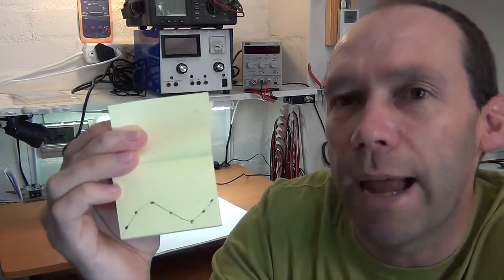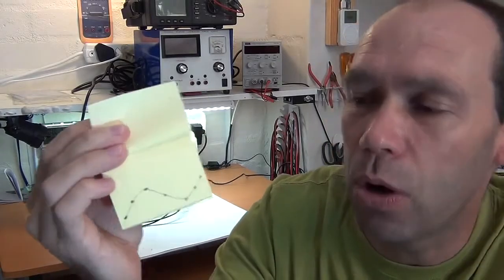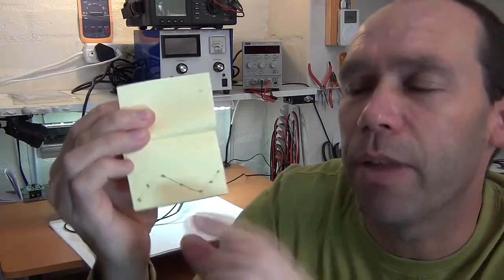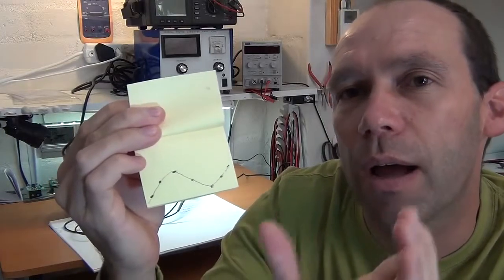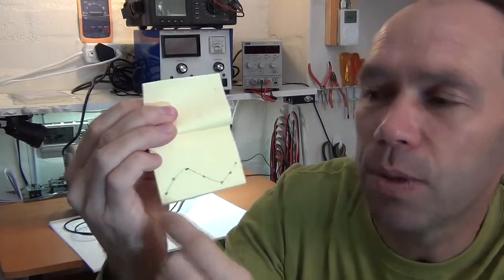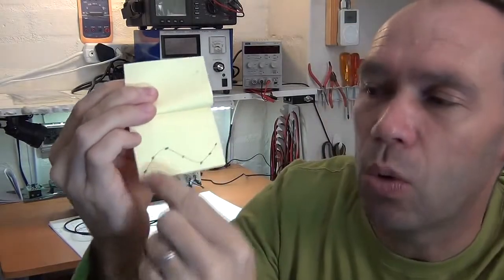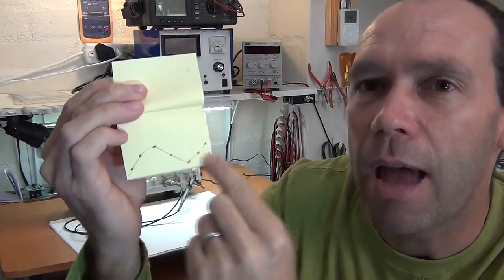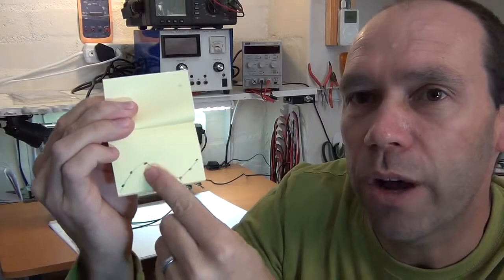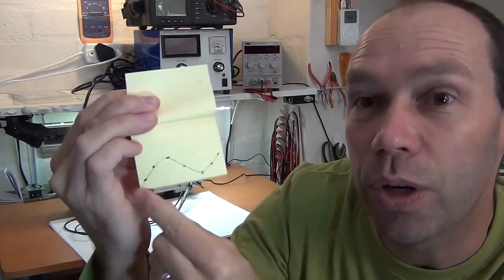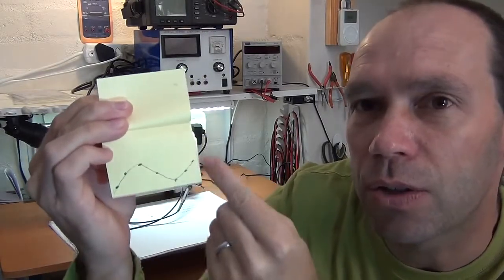And in essence, that's exactly how the old analog oscilloscopes work. They have a measurement and they use those old CRT tubes, cathode ray tubes, and it would alter the beam, or the trace as it would be called, as it got a signal. And because of your persistence of vision, your eye, it would actually draw a trace and join the dots, or join the individual measurements across the screen. And that's in essence how the original oscilloscopes worked.